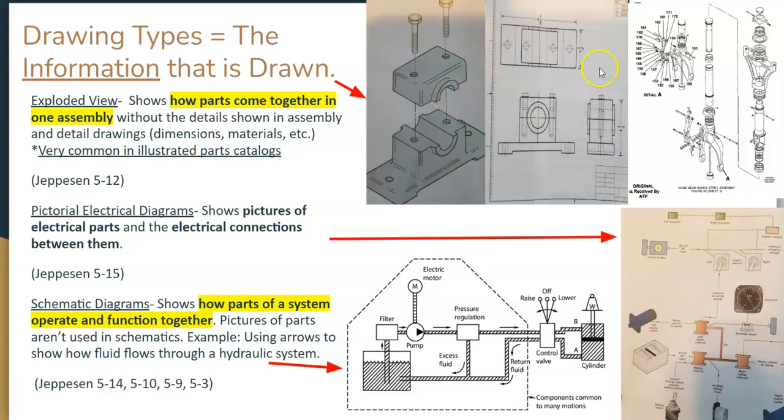And this isn't an exploded view, this is actually an assembly drawing. You can see that this very same thing is drawn here orthogonally, which means that it took that 3-dimensional object and put it into 2-dimensional views. And you can see the holes for the top and for the sides like you see right here, and you can see hidden lines marking where the bolts are going to be. You can see where the top and the bottom come together and how there's a line separating the 2 pieces.